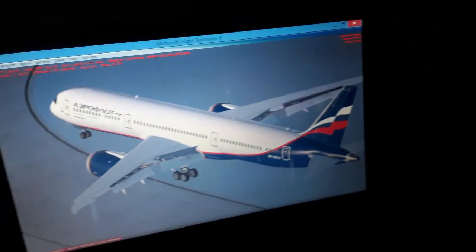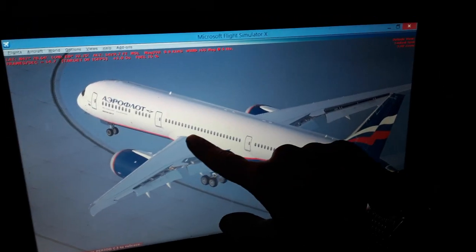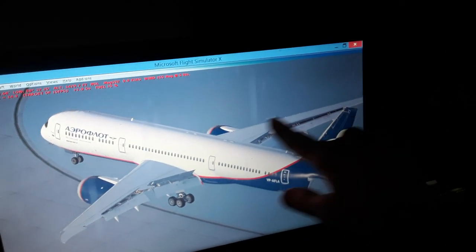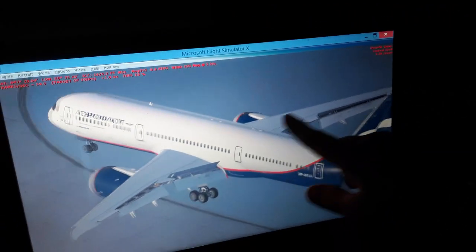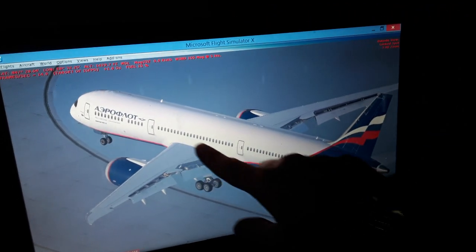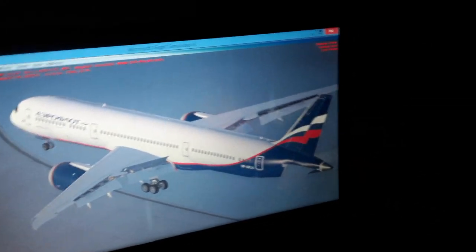Also, you can see we have the mean aerodynamic chord position, the MAC, which is 23% of the mean aerodynamic chord over here. This is where the maximum aerodynamic lift occurs in the forward wings, also the position where the center of pressure is moving back and forth when we fly. Also where the stall will begin in flight.